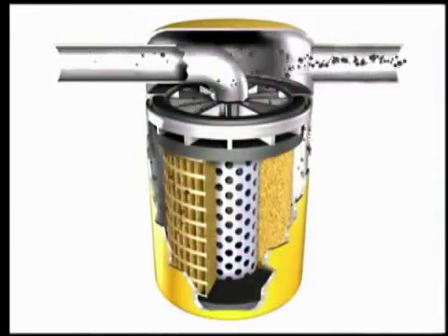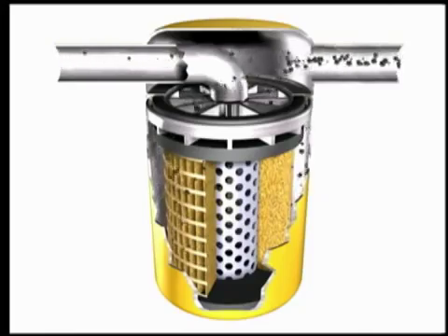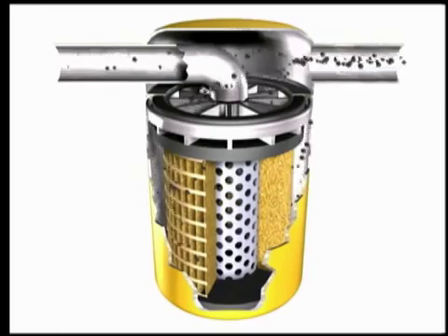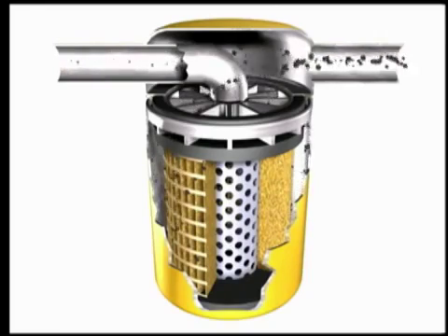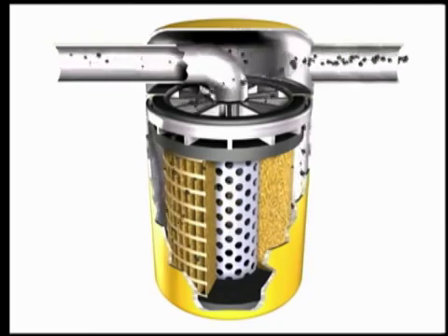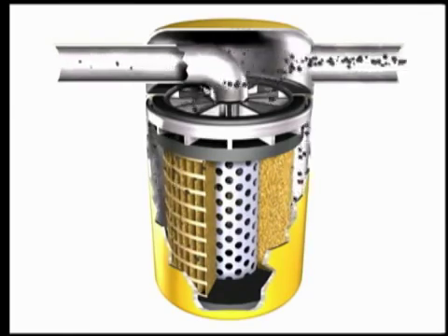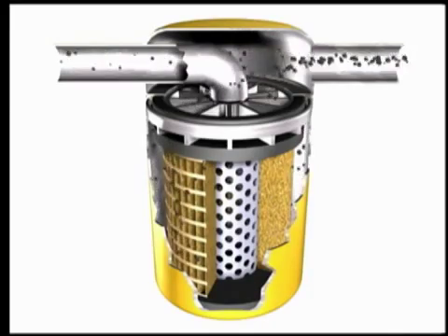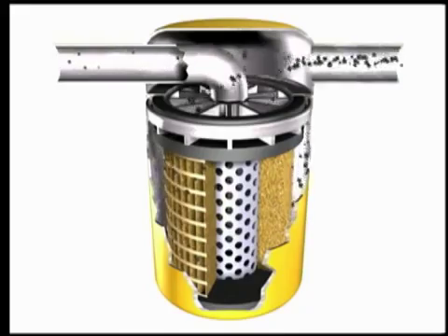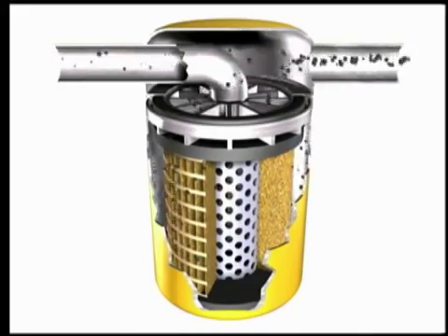All these particles then move on to the filter. Do not assume the filter removes all contaminants in a single pass. As the oil moves through the filter media, many of the particles are trapped, but a few, some large and some small, travel through the media and return to the system through the center tube. Even high-efficiency filters do not remove all contaminants.